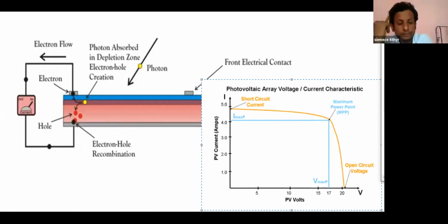The battery is also connected to the inverter, so that when the solar cell cannot convert light into electricity, the battery can supply power. The power grid line should also be connected to this inverter, so that when the solar power or battery backup is low, the power grid can be used.